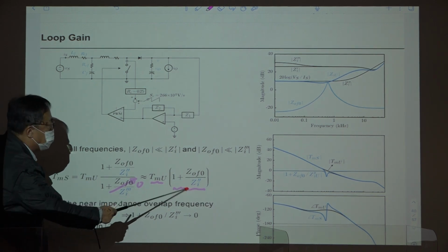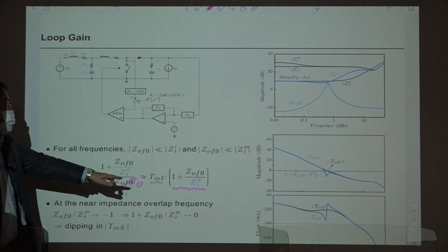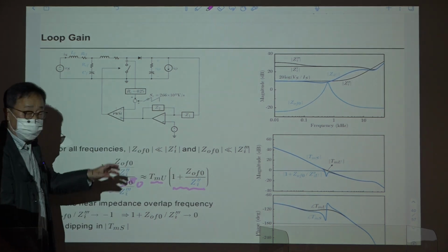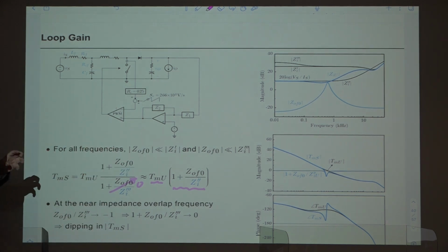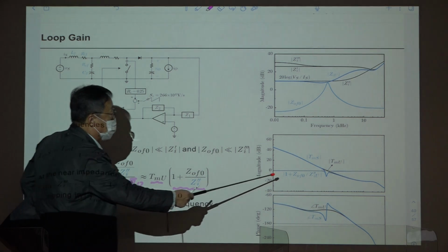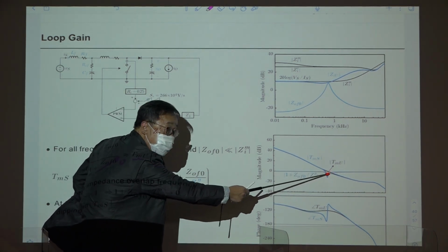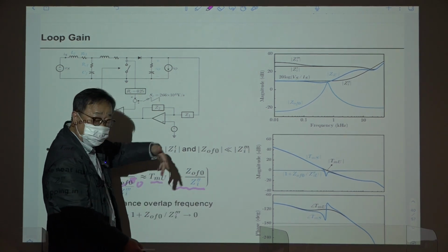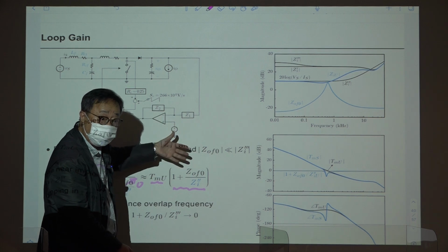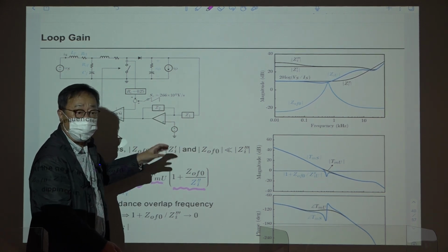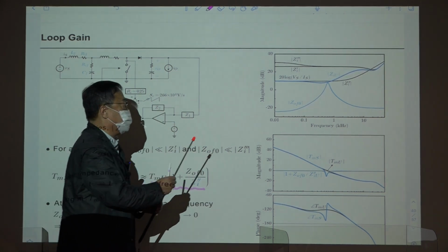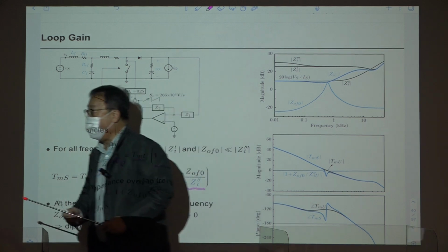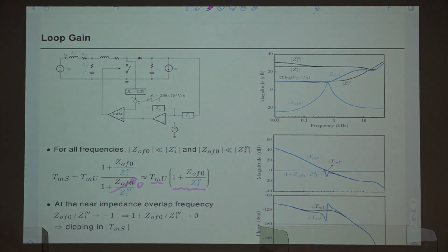They are out of phase. So it becomes very small, but this time, this term is coming in the upstairs. So what are we seeing? A dip in the loop gain. So the dip occurs here. Right? So this is very dangerous. Of course, the previous analysis says that the converter is on the verge of instability, but in this case, this directly shows the phase margin is running out.